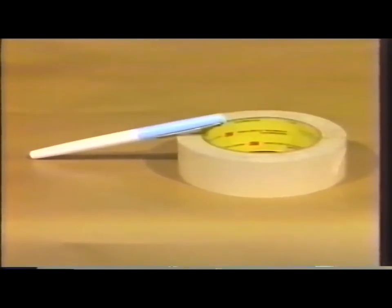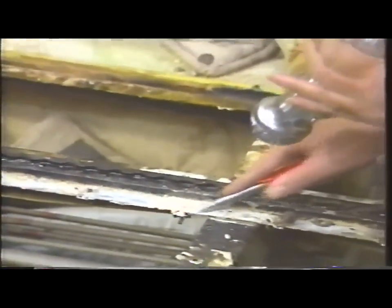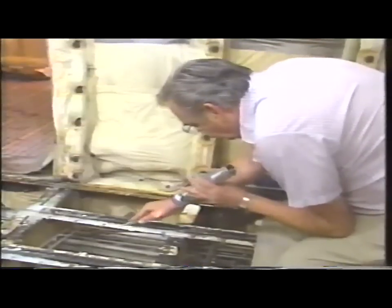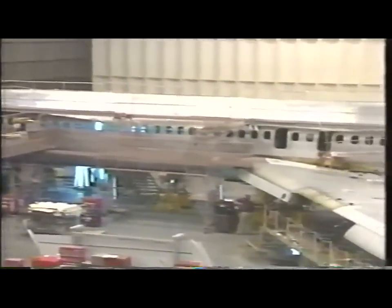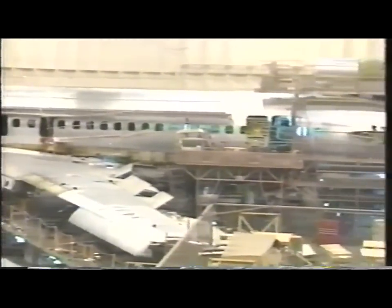If you are going to do a good job inspecting your aircraft, you need to be able to recognize materials, proper coating, and damage which could lead to corrosion. This section is devoted to common aircraft metals, coatings, and their corrosion products. The primary metal used in manufacturing aircraft skin is aluminum alloy sheeting called Alclad, or simply clad. Although clad is highly resistant to corrosion, pitting can occur if inspection and routine maintenance are not performed.